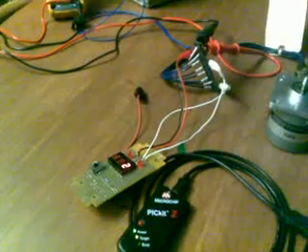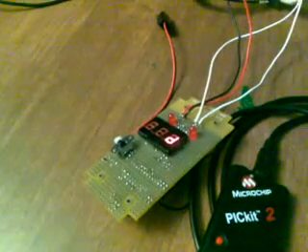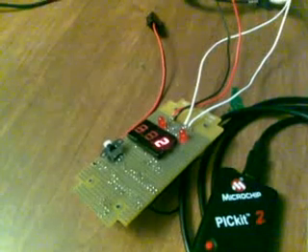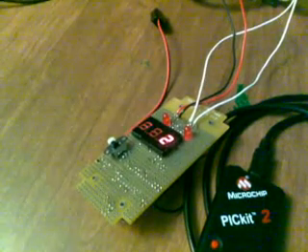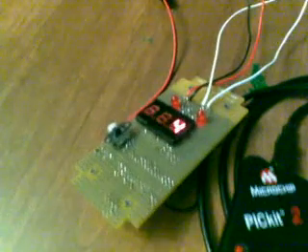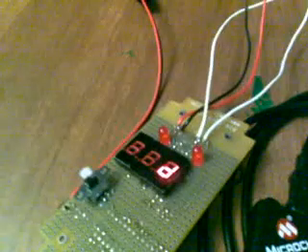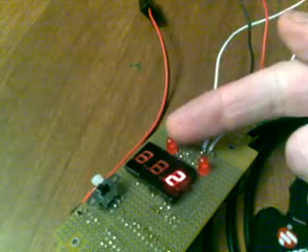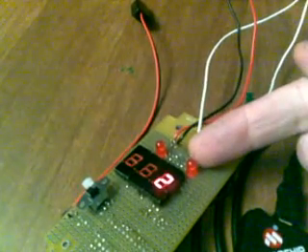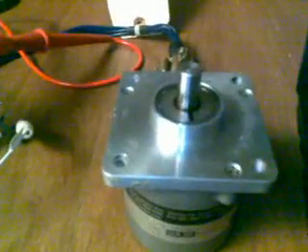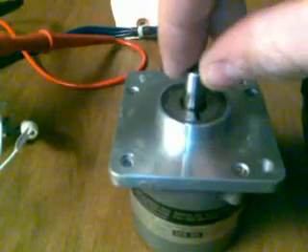So the next revision will be probably powered off of an AC to DC converter, something you can plug into the wall, and it'll have probably a larger PIC that I can plug 5 7-segment LED displays into, so it's more user friendly. And also these LEDs here, one will light up when the power's on, one will light up whenever it sees a marker pulse, so that you won't have to strain to see the line that's drawn in the shaft here.